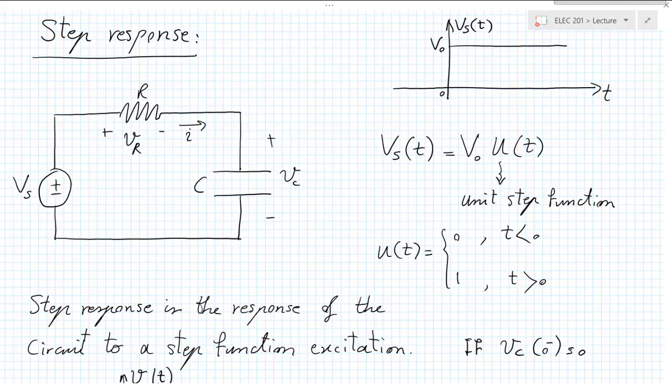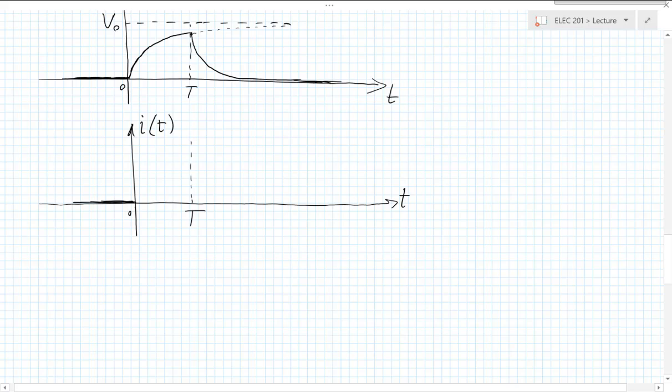So I'm not a huge fan of using the term wire at that moment for this, you see. Because when we talk about steady state, an inductor being like a wire, that's for an extended period of time, and there is less chance of confusion. Here, it's really just at that moment that it has no voltage. So it could maybe lead to misunderstanding. So I'd rather just say, at that moment, the voltage is 0, and the entire voltage drop is on R. And so the value of the current is V0 over R.